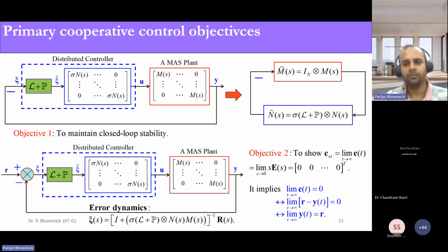can first be linearized or it gives a reduced order linear mapping, and then we can design a distributed controller keeping ourselves in the linear domain or in the S domain. If you use other nonlinear cooperative control techniques, the theoretical steps are much more rigorous. The calculation, the comprehension, and also the implementation are really very challenging. So if you follow this technique or this kind of mechanism, we are simply extending our classical control concept into the multi-agent framework.